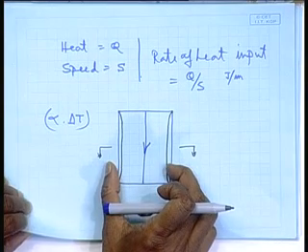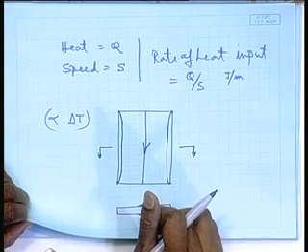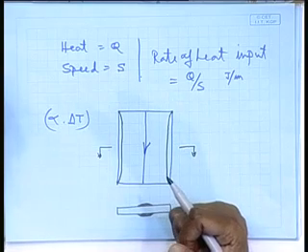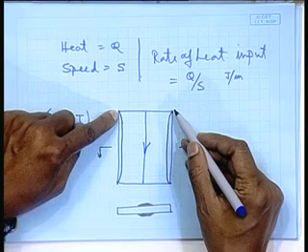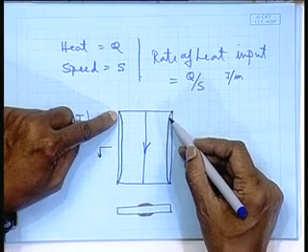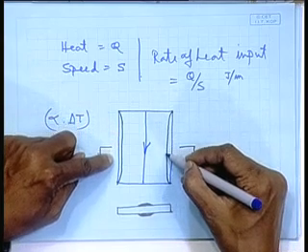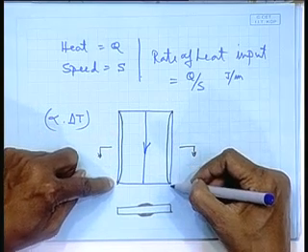So first we said that we may observe that it has shrunk. Why it is shrinking is well understood. That is, shrinkage forces are developed, so it is getting that offsetting effect, as if I am forging it along the breadth, right. So it has become narrow. Now why I have drawn it like this: it remains at 0 somewhat, because the shrinkage forces were nominal at the starting point, much less, then gradually increased to maximum, then continued to be uniform, and again tapered down to 0.